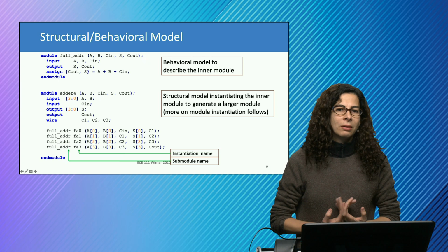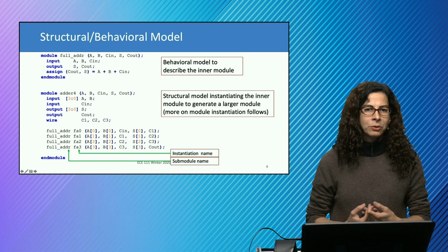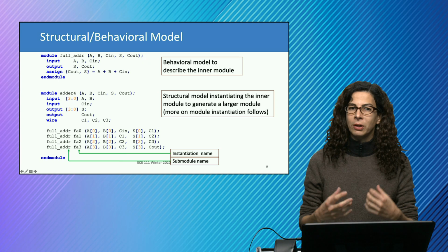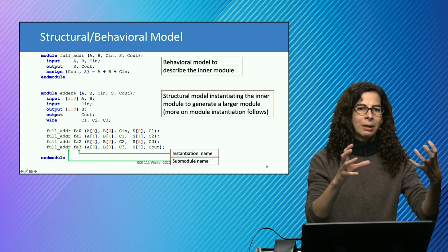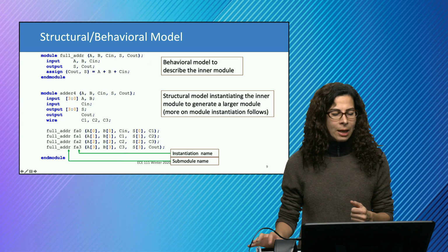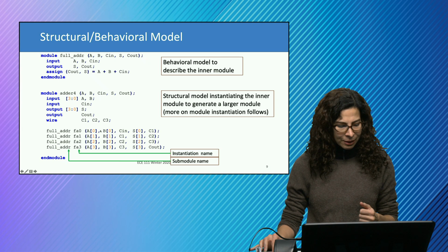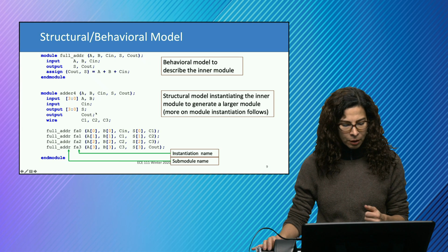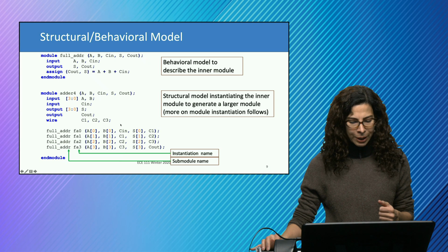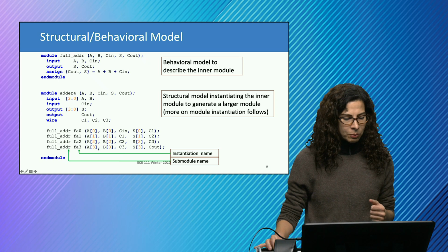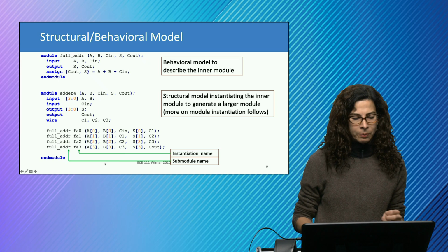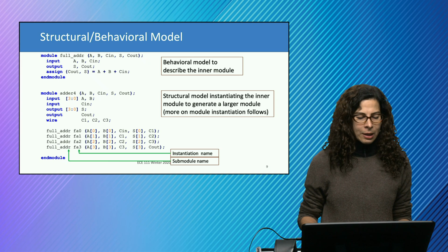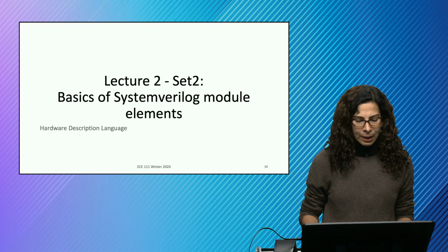So we need to be very careful about this, because every time you call a function or put a variable, we are basically putting a register or a piece of logic in the design. The wires here are just connecting the 1-bit full adders to each other, and this way we can write this small structural design in Verilog.